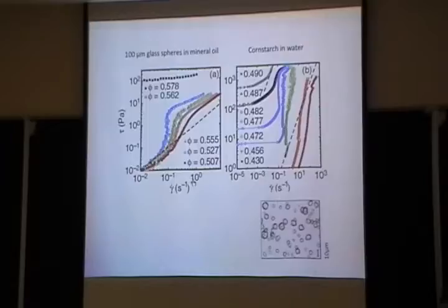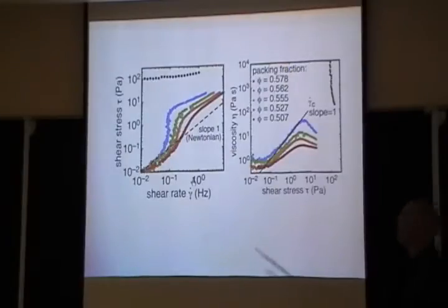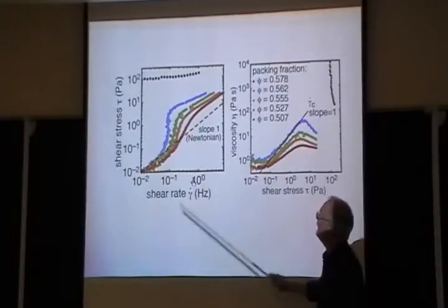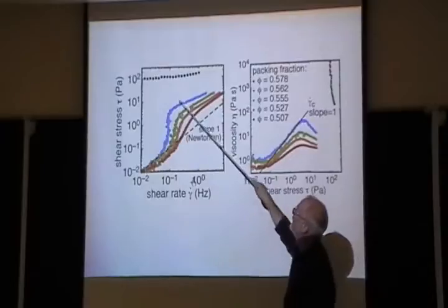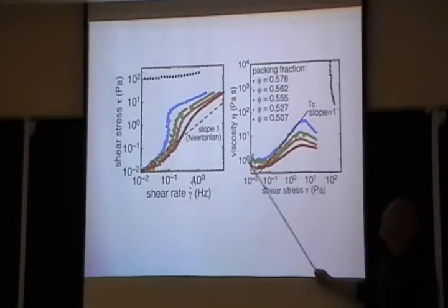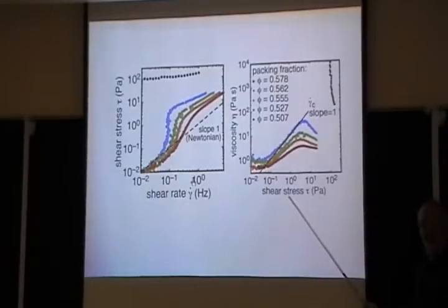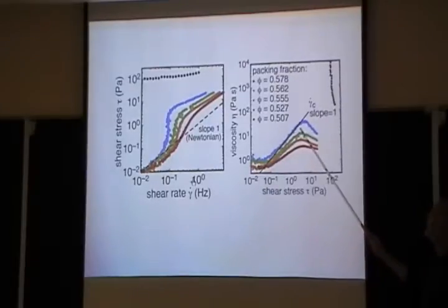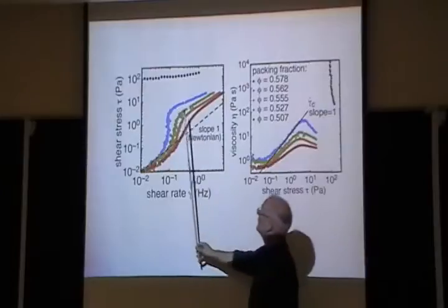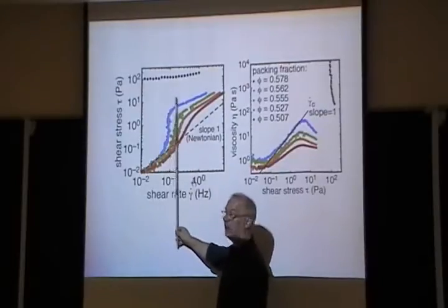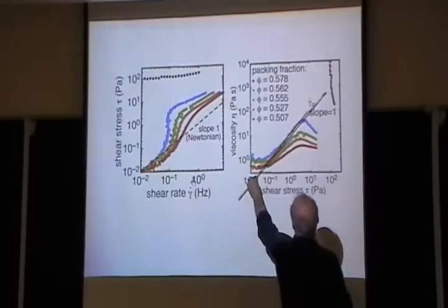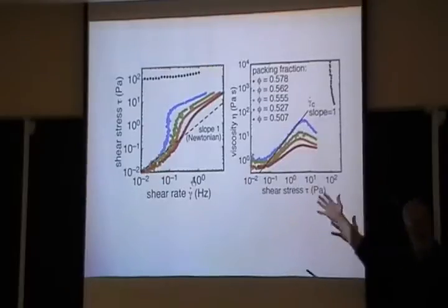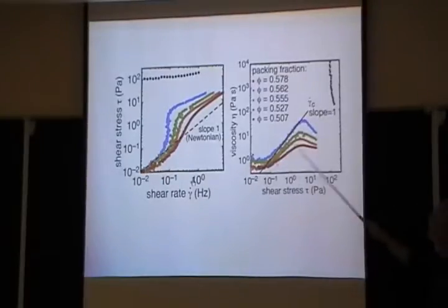So now let me take these plots and just plot them in this other way as viscosities, right? It's a simple thing. I just take the one that was glass right now. So this is the original plot I just showed you. See how it jumps up there. Now I plot it as viscosity versus shear stress. This is what we talked about earlier. So this data turns into this data, and the slope that's essentially vertical here turns into a slope that is 1, right? Just too familiar with. So that is discontinuous shear thickening.